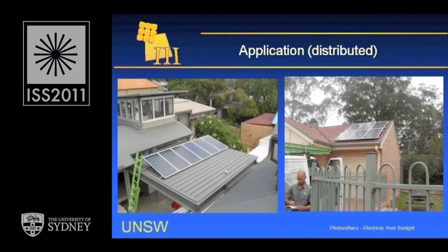In this system, the conversion efficiency of the panel is not 100%. It turns out that there's a fundamental theoretical limit on the performance of the panel of about 30%. So that's a fundamental limit. The actual panels are about half that, so about 15% efficient. So rather than this being enough to provide for 2 households, it'll provide about a third of the electricity requirements of an average home. So if you put 3 rows like this, this would provide the whole electricity requirements for the house.